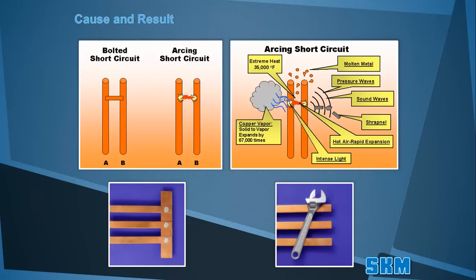Arcing faults occur when the current passes through the vapor between two conducting materials. These high-temperature arcs can cause fatal burns even when standing several feet from the arc. The electrical arcs also shower droplets of molten material in the surrounding area, causing further hazard. The arcing fault current is smaller than a traditional bolted fault current because the vapor acts as an impedance between the conducting materials.